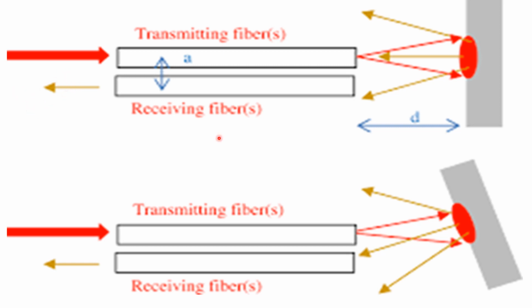displacement. Also, with the help of intensity, we can find out the displacement. So here the optical fiber's role is only acting as a wave medium, that is, a guiding medium. Through this it goes and through this it comes out. It does not involve itself in determination of anything. So this is an example of a passive sensor.